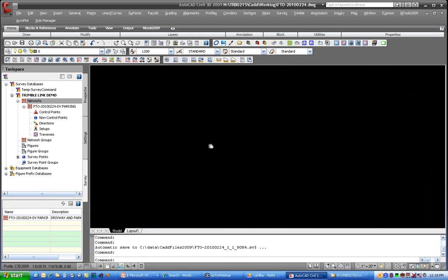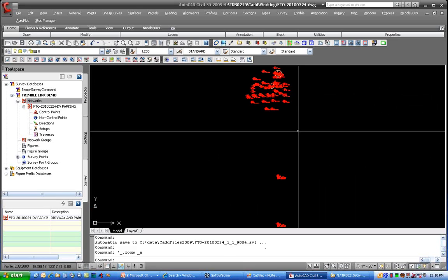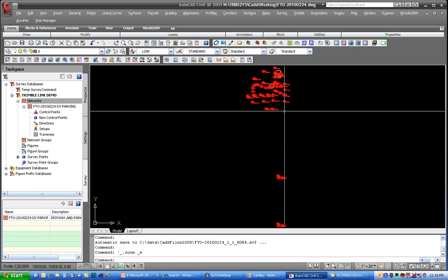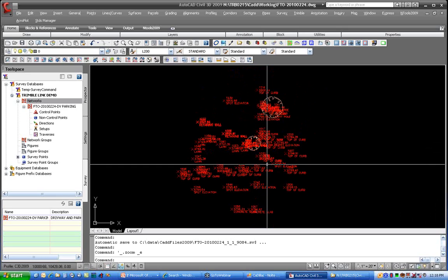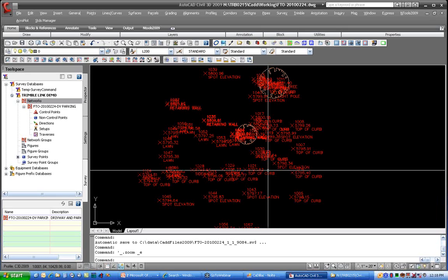All right, there's my one control point, oh, I got rid of that one. All right, so we've got our point data here. We've got a few control points that we don't need to see, but we brought it in, and for some reason, I don't see figures. I had that turned on, didn't I? Let me check layers real quick.